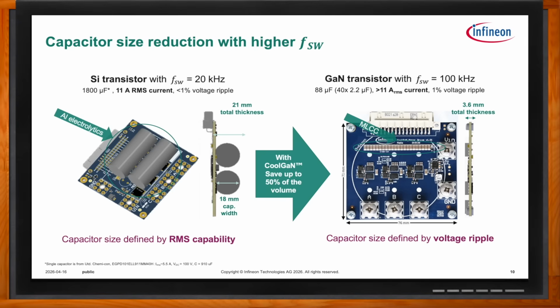Why? Because these capacitors are rated for a specific ripple current. And on these, I'm really at the limit, even with these two big caps, because each is rated at about 5.5. So I'm right at the limit with 11 amps of motor current. And the reason is because it creates self-heating inside of the electrolytic cap and reduces performance. And you get losses, right? I mean, electrolytic capacitors are not lossless. So it's big. I'm going to suffer losses and they're going to heat up.